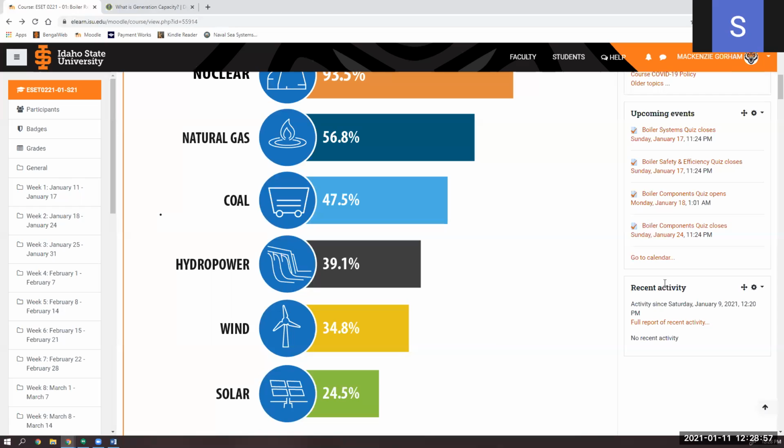None of these move quickly, which is why we don't typically do what's called load following with our baseload power. We talked about the morning when you wake up before you go to work, and then when you get home in the evening, there's that load that increases, there's demand, right? A little bit coal, but a lot more of these types of energies can supplement that load following. They're working on new modern plants for gas and coal that can load follow. And there's the hope that small modular reactors can load follow.